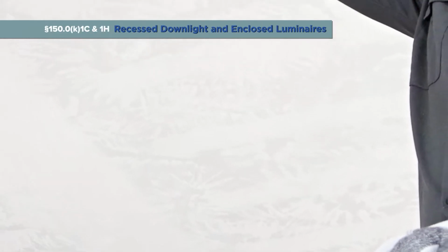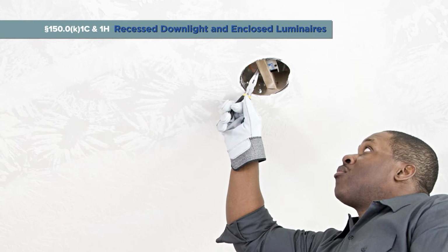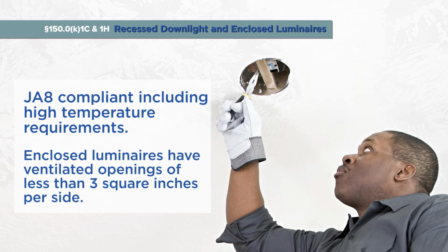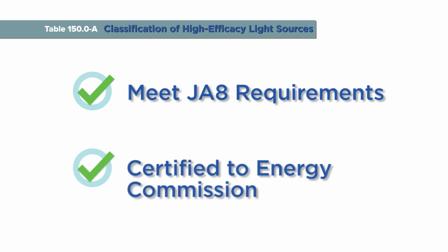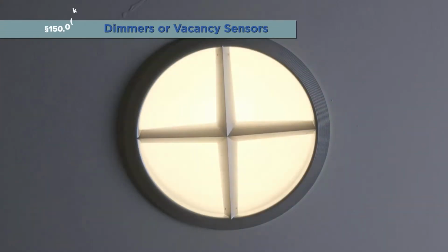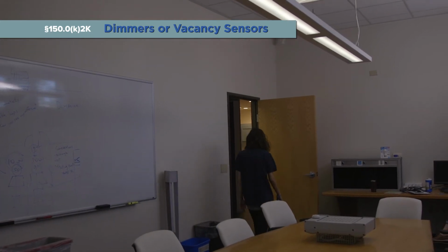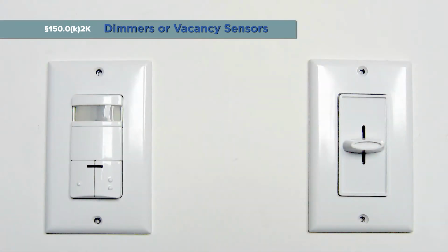Other types of recessed downlight luminaires and enclosed luminaires must contain a light source that complies with JA8, including the elevated temperature requirements. An enclosed luminaire is defined as having ventilation openings less than 3 inches squared per side. Light sources which are automatically qualified as high efficacy must still meet JA8 requirements and be certified to CEC if they are used in a recessed downlight or enclosed luminaire. There are also mandatory control requirements for luminaires with JA8 compliant light sources. All luminaires with JA8 compliant light sources must be controlled by a vacancy sensor or manual dimming control.